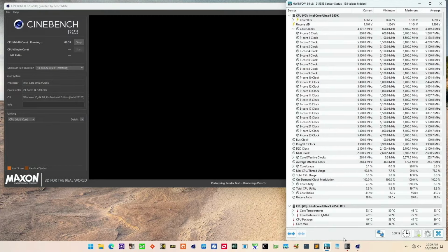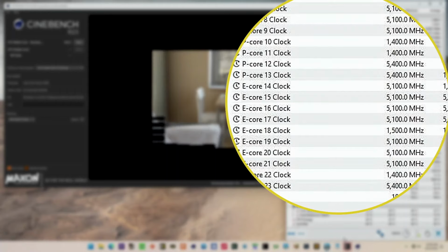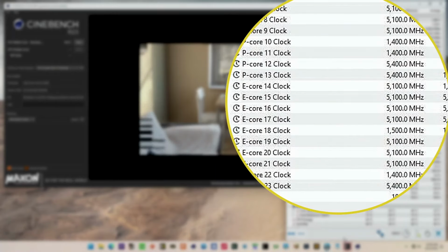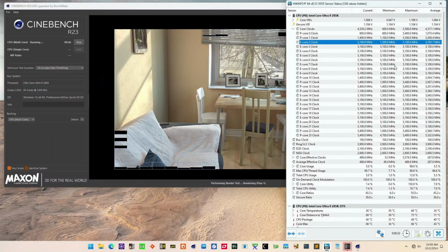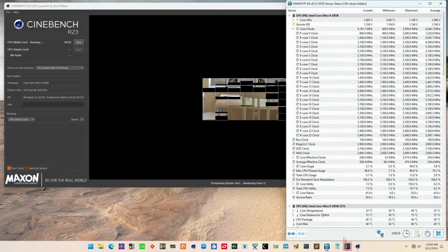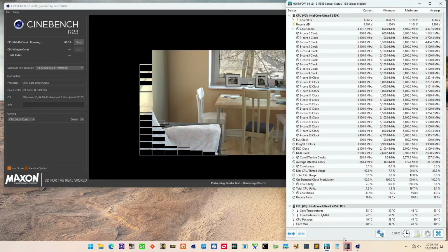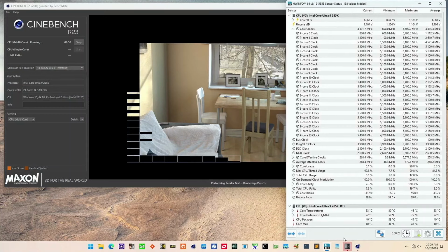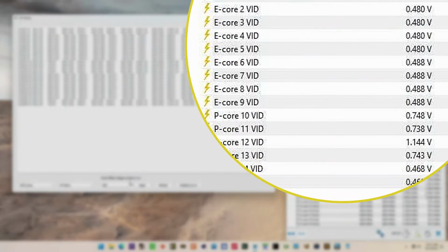The E-core overclocking range is also quite good. With 1.25 volt, I could increase the E-core frequency to 5.1 GHz in Cinebench R23 with a 360 AIO. That's a 500 MHz increase from the base frequency of 4.6 GHz. The cores can reasonably undervolt as well. I could achieve a minus 75 mV undervolt at 4.6 GHz, effectively reducing the operating voltage from 1.078 volt to 1 volt. At the lower end of the VF curve, I could even undervolt the cores to below 0.5 volt at 400 MHz.